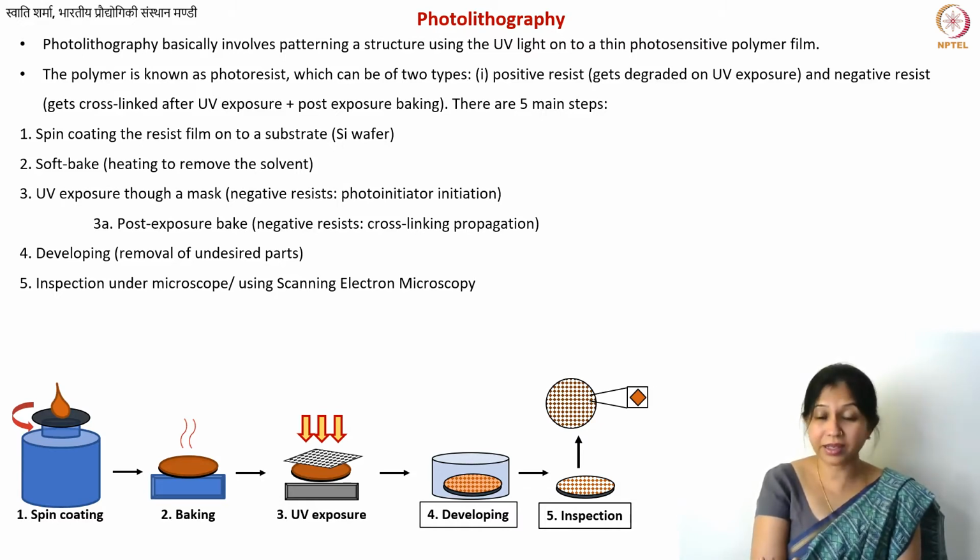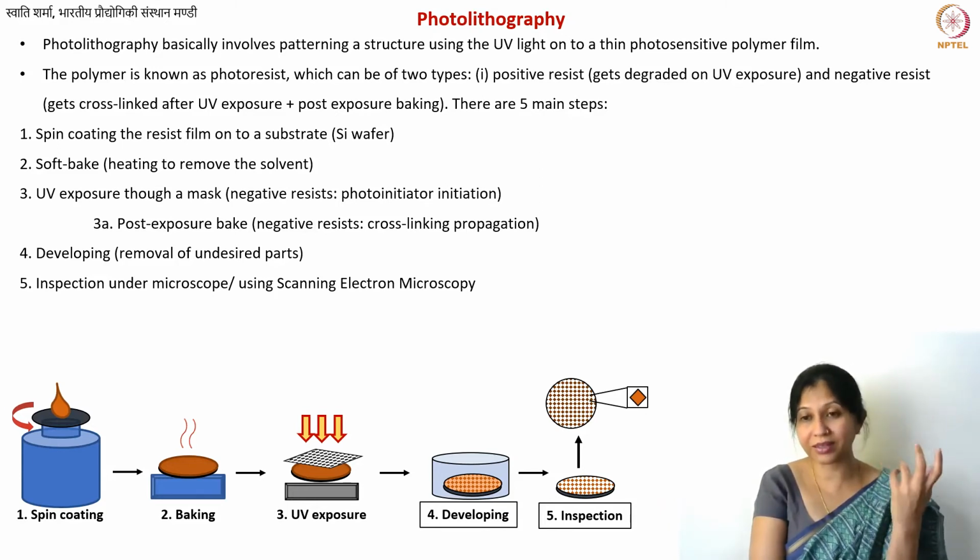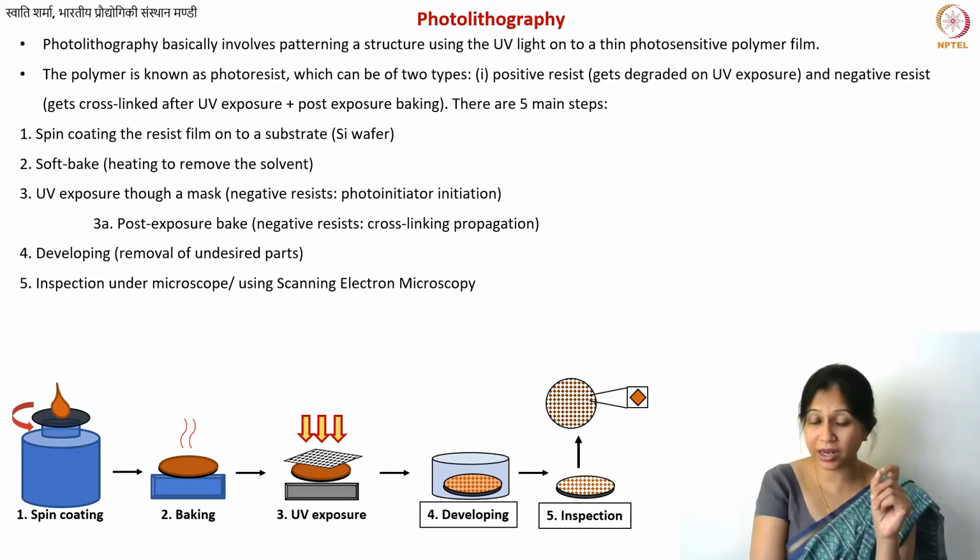Other things such as electrical conductivity are also within the same range as what you have for large-scale structures. Mechanical, so Young's modulus is also in the same range. So most of the properties are similar to commercial glass-like carbons when you get glass-like carbon from photolithographically patterned structures. Now, specifically in this particular case, I would like to mention a commercial name.